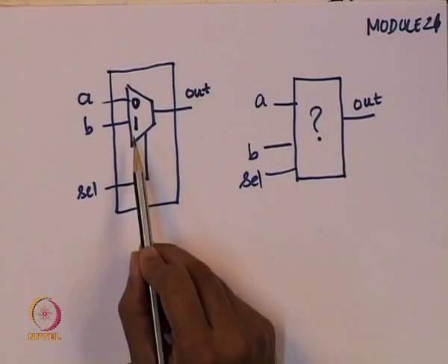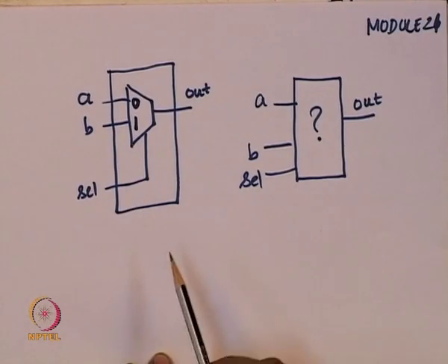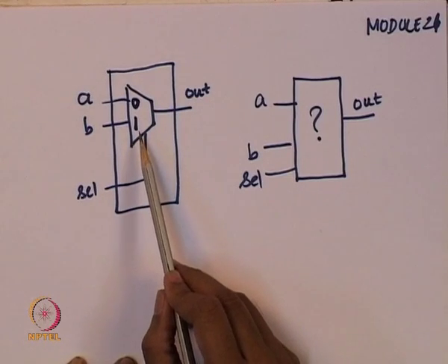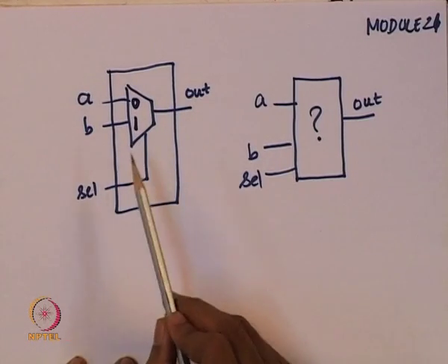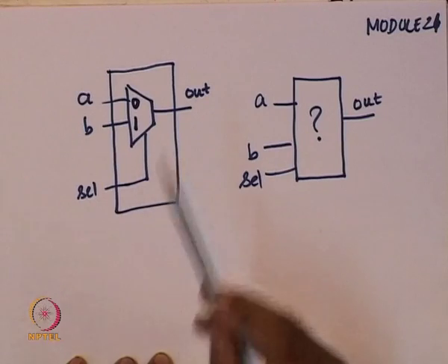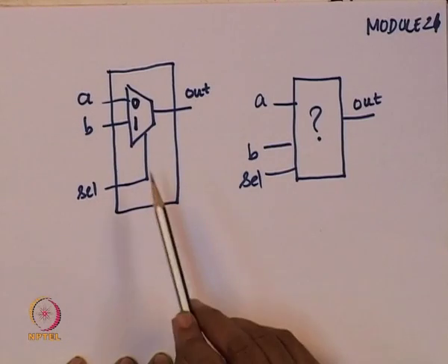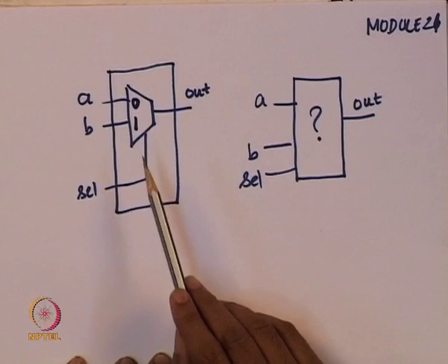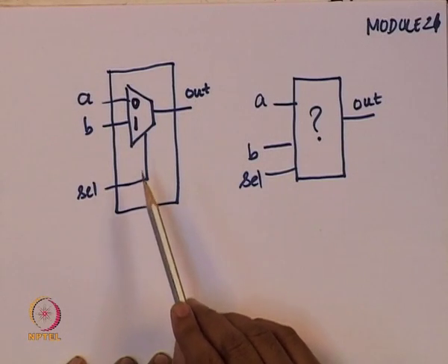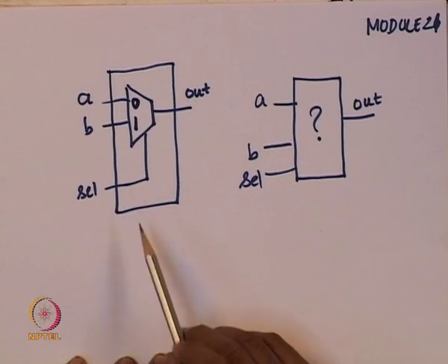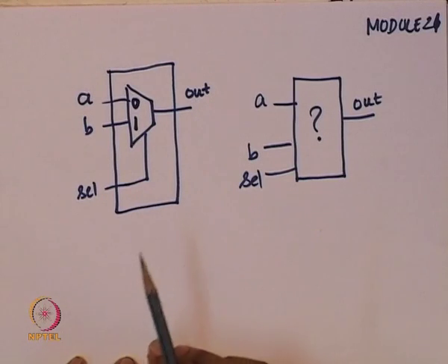One thing you can do for this particular multiplexer is, you know that a multiplexer can be implemented using AND, OR and inverters. We already discussed this in last week's Verilog demonstration, where we saw how to use the primitive gates or primitive data types, like AND, OR and so on. We can use those primitive structures and write what is called a structural description.